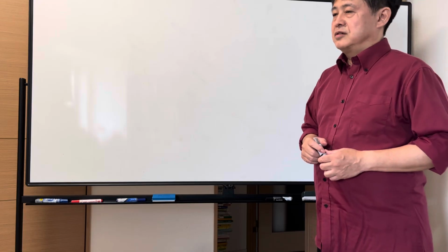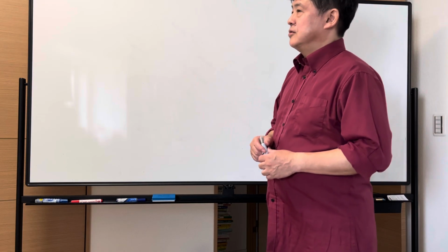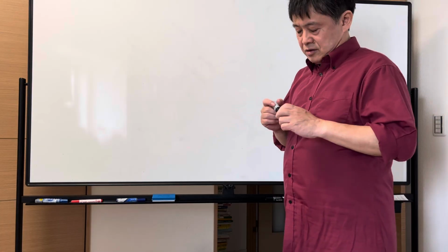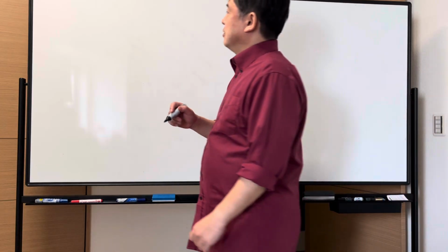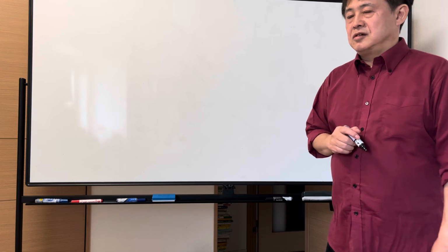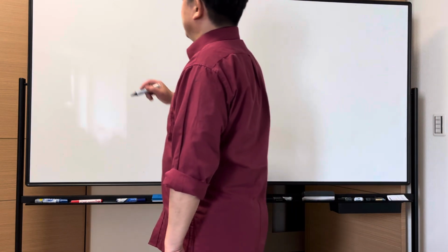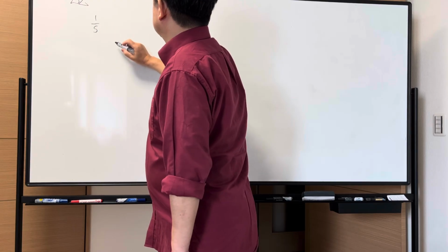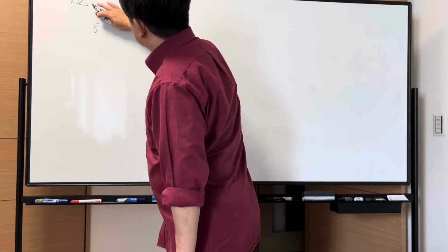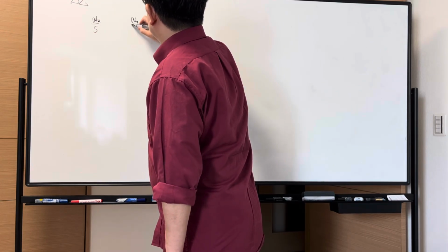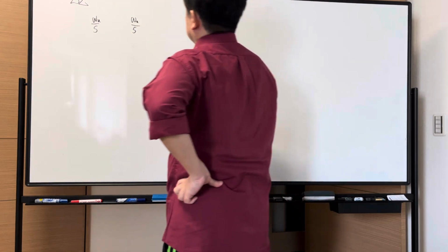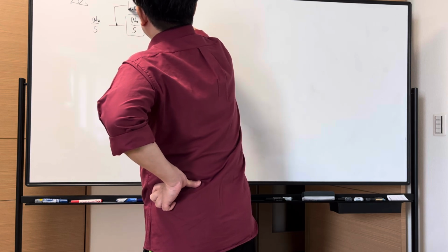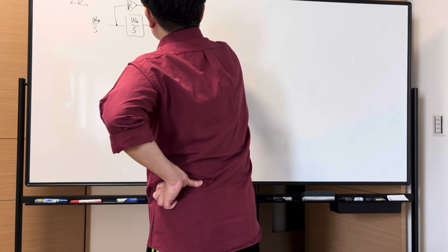Especially at first, I'd like to comment on the phase noise from the VCO, focusing on it like the quantization noise in a delta sigma modulator, because the topology of both looks the same. For the delta sigma modulator, we have an integrator, a two-stage integrator, with unity gain frequency omega sub u. The same topology is cascaded, but in the second part, the second order delta sigma modulator has a feed forward path in the second stage.